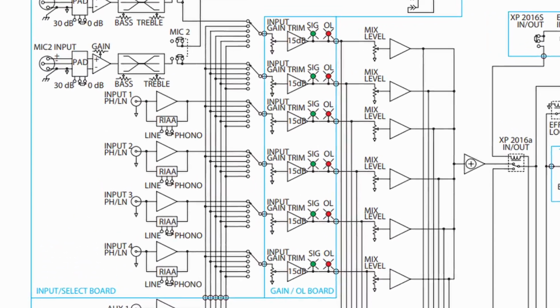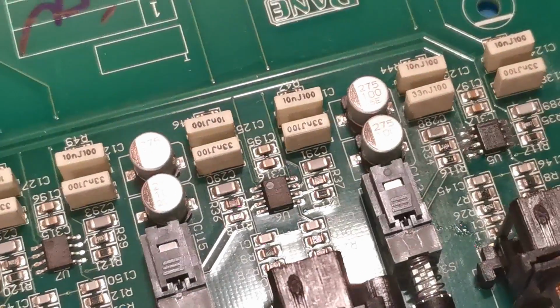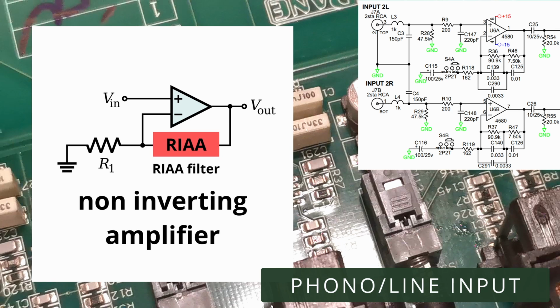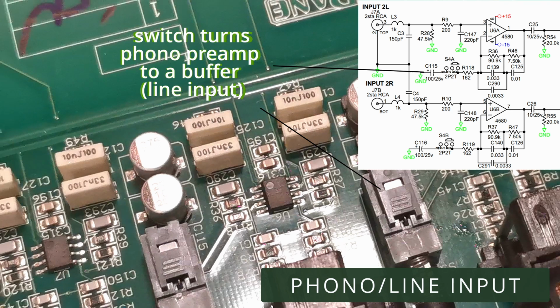Now let's take a look at phono line inputs. There are 4 phono line inputs here. Phono and line stages share a common connector. Phono preamp is a well-known single-stage active solution. I can finally show you what it means. Phono amplification is done by a single non-inverting amplifier that uses a RIAA equalizer in the feedback loop. That's why it's called active. By changing the switch position you set the gain to unity and transform phono preamp to a buffer.